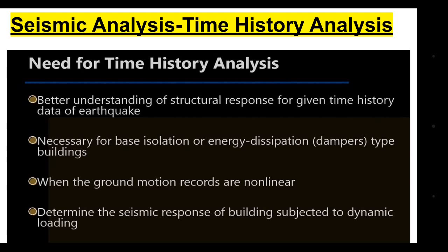Now our third topic is seismic analysis by time history analysis. First, the need for time history analysis: better understanding of structural response for given time history data of an earthquake, necessary for base isolation or energy dissipation type buildings. When the ground motion records are non-linear, determine the seismic response of buildings subjected to dynamic load.